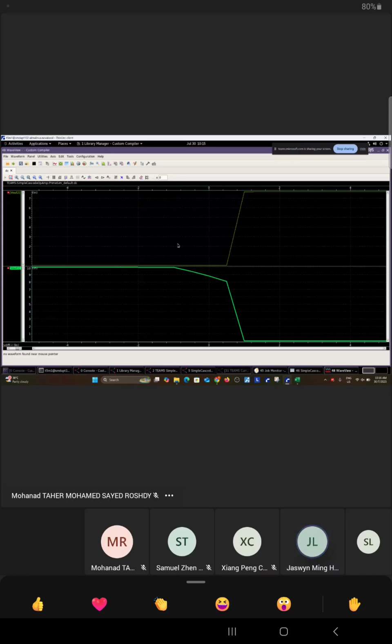So as I said, the best working region for your op amp is where your output voltage increases linearly with input voltage, right? The more your input voltage increases, your output voltage also increases by a certain proportion. It means that you have a constant gain throughout the region. And this is where your gain gets clipped off.